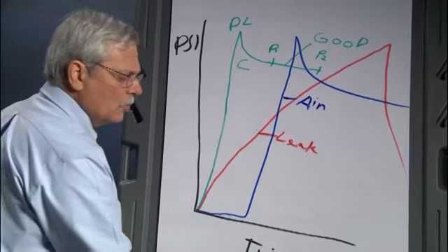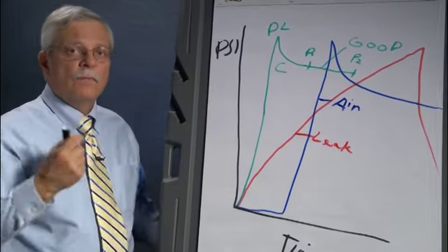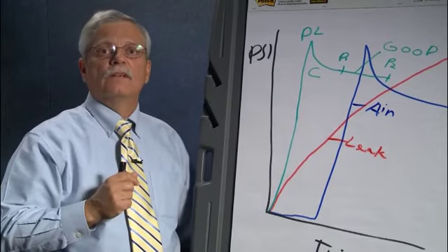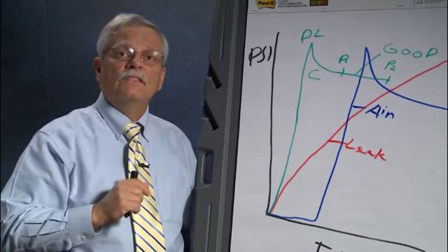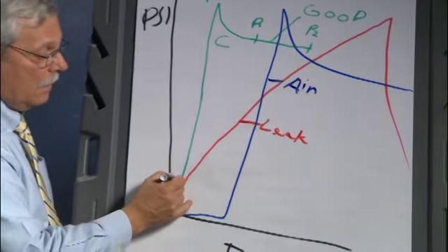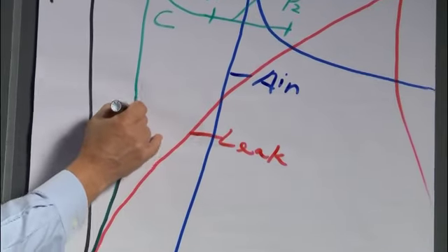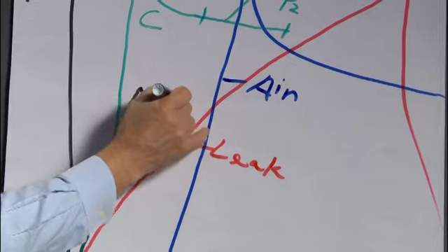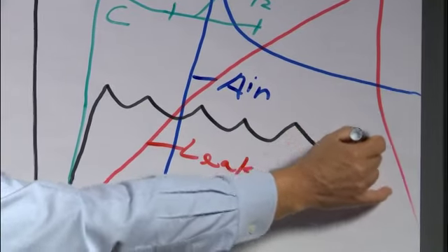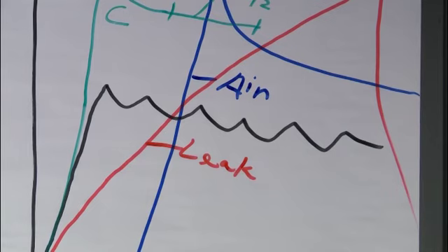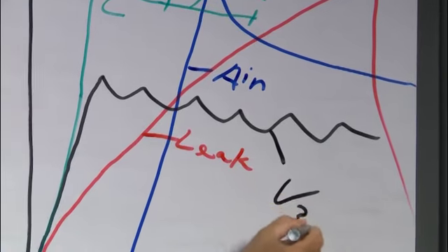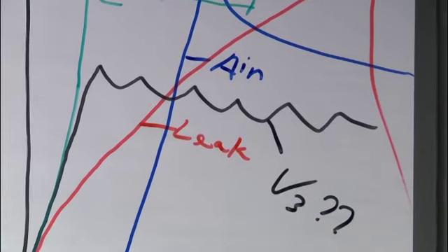One other thing that can occur. Valve number 3 is a solenoid valve. It's designed to open up at about 400 psi. But if the valve is damaged and it opens up earlier, the pressure will rise up to a point, and then all of a sudden, the valve starts opening and closing, and the pressure never gets any higher. So valve 3 is questionable.